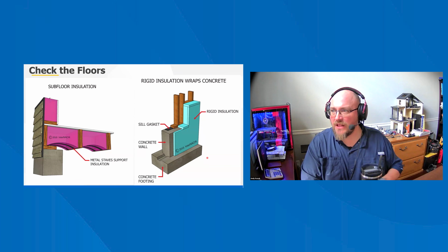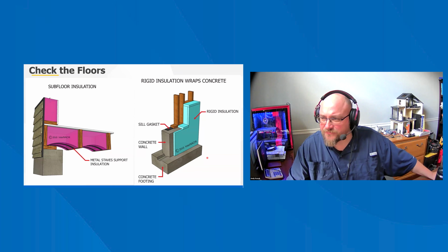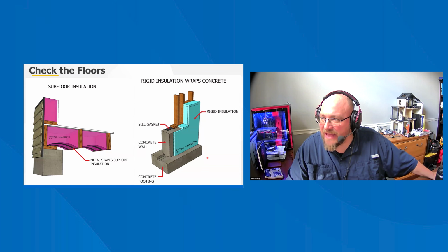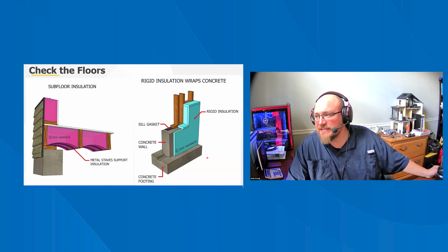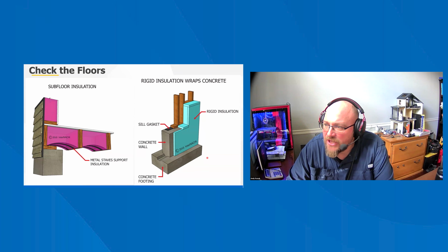Look at the underside of any floor that is located over an unheated space, such as a crawl space, basement, or garage. Check and measure the insulation that is installed there. It will likely be fiberglass batt insulation. The insulation may be identified with its R value printed on it. If it's not, multiply the fiberglass batt thickness by 3.2 to figure out its R value. If the insulation is foam board or sprayed foam application and you can't find any labeling, you can multiply its thickness in inches by 5 to get a good estimate of its R value.